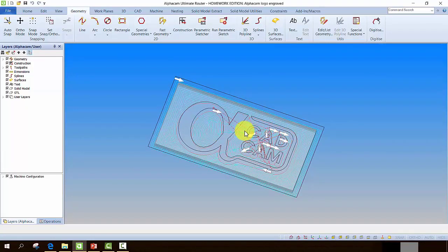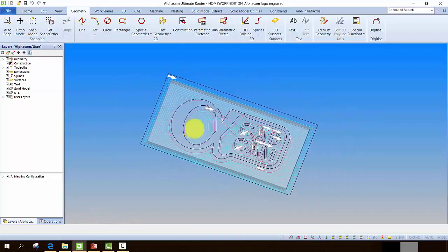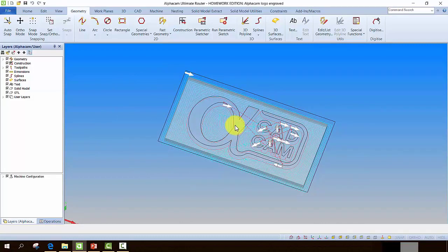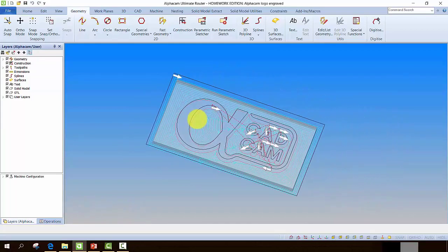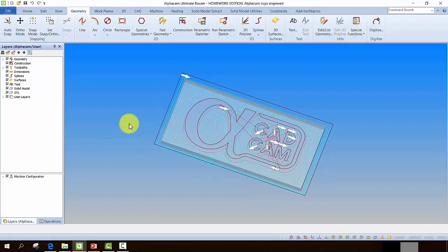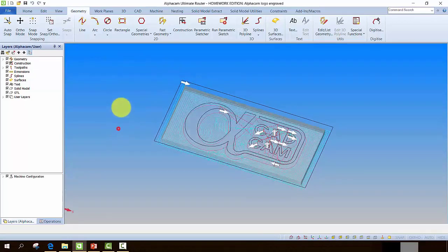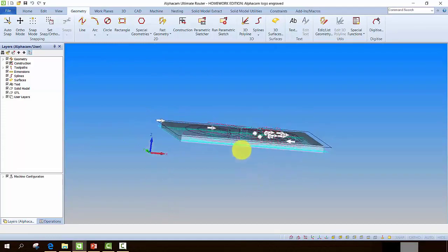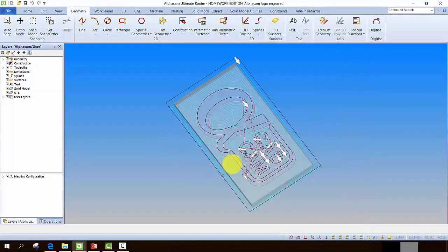So in terms of navigating your way around the screen, to pan left and right, you simply depress the mouse wheel. Those of you with knowledge of Inventor will find that's the exact same command that is used in Inventor. It's not one of the regular left or right click buttons, it's actually the button integrated into the scroll wheel on the mouse. To rotate, it's just a regular left click somewhere in the background. You don't use the same system as you use in Inventor. You simply click and drag a blank area of the screen, allowing you to rotate it as you see fit.